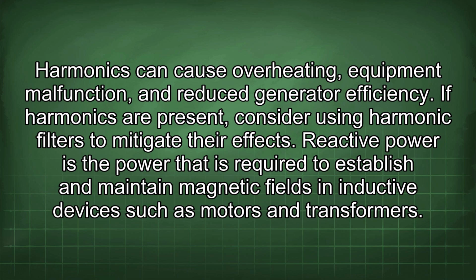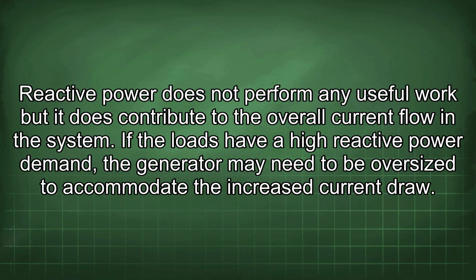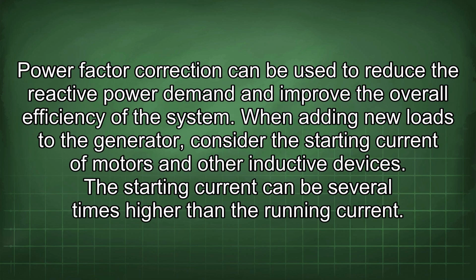Reactive power is the power that is required to establish and maintain magnetic fields in inductive devices such as motors and transformers. Reactive power does not perform any useful work, but it does contribute to the overall current flow in the system. If the loads have a high reactive power demand, the generator may need to be oversized to accommodate the increased current draw. Power factor correction can be used to reduce the reactive power demand and improve the overall efficiency of the system.